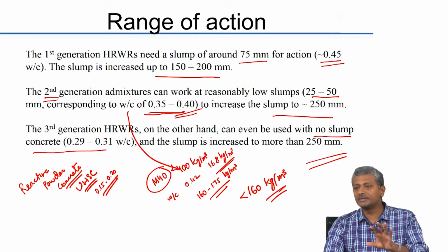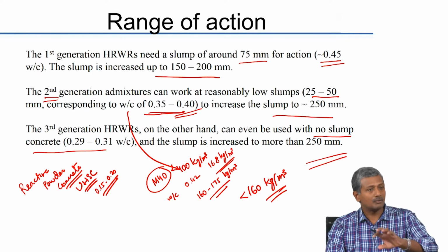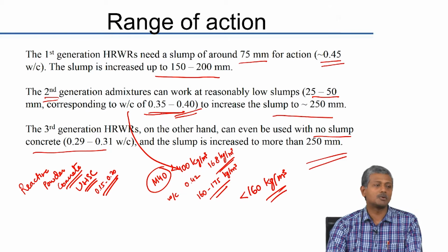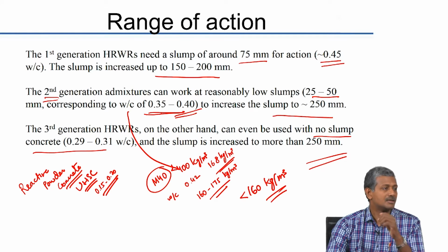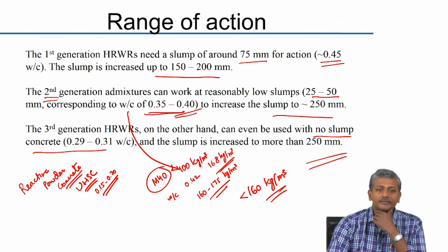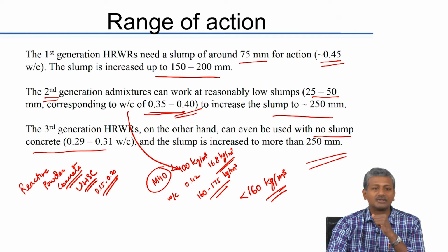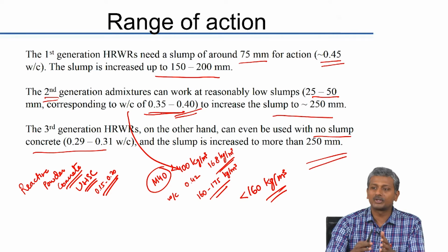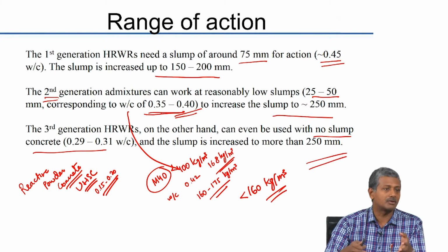So again, please remember, when the superplasticizer is added to the concrete, you have all seen in job sites when superplasticizer is added, at what stage is the SP added to the concrete? Along with the water or right after the water, right? With part of the mixed water, you mix the superplasticizer and then you add to the concrete.